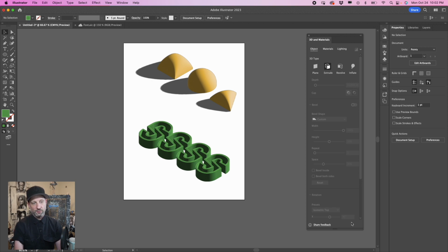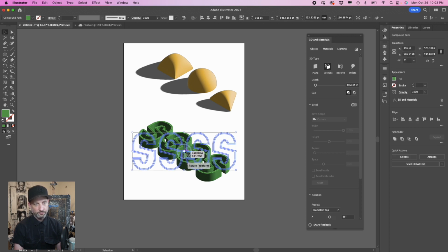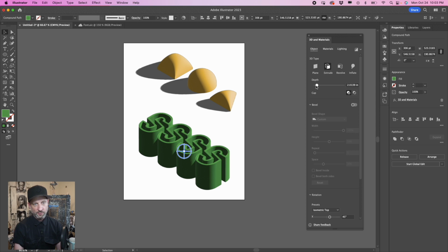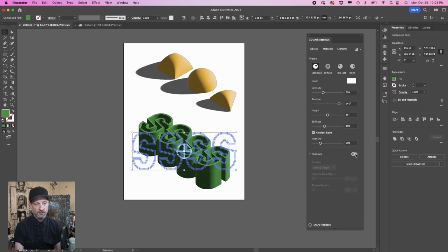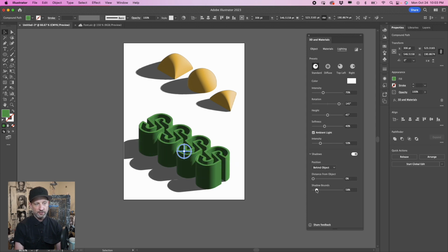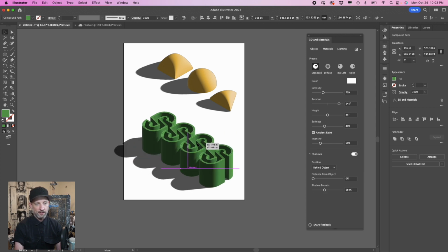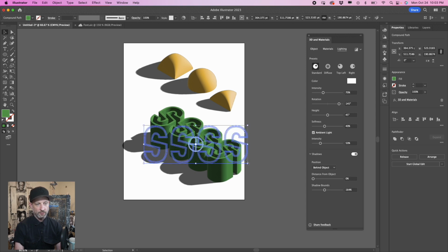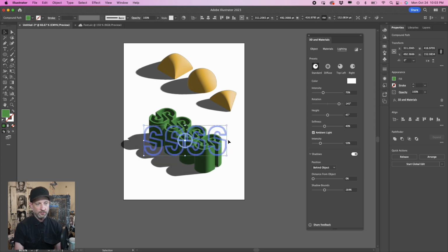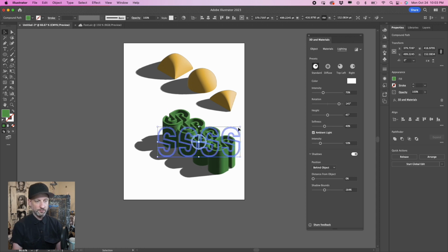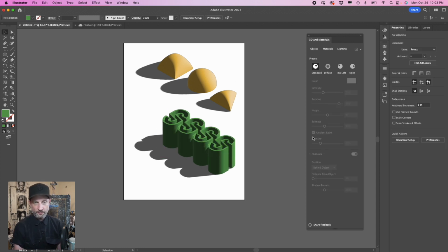So we're using the isometric top again, and same deal. In this case, if we want to make our text taller, we can. Let's make them a little bit taller than before. So now they're taller, and then let's go ahead and go straight to our lighting this time and do the same thing. Turn on our shadows, open our bounding box a little bit more, and then maybe we make it a little bit smaller so that shadow fits inside of our work surface, and that's it.